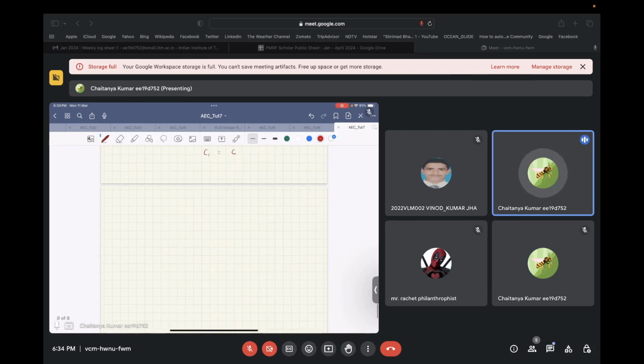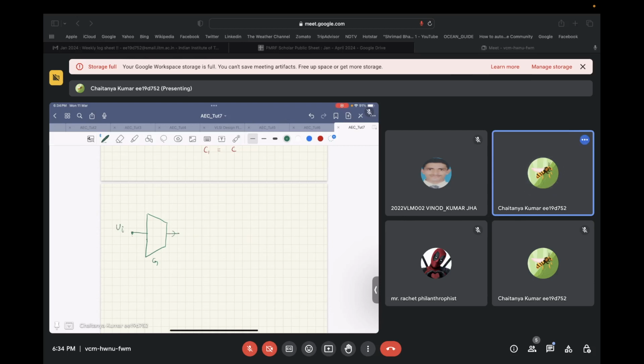So we will put the complete circuit into place. For the current source, we have 1G over here. Input we provide over here. There's a resistance with value 1 by G. Then we have a capacitance over here. And this is basically emulated as follows.